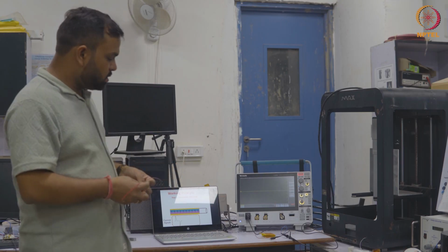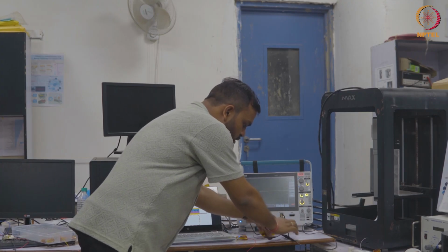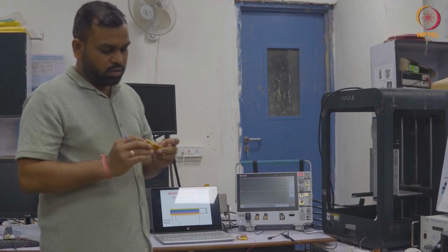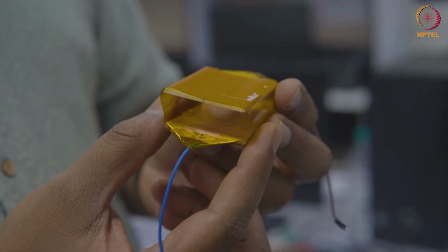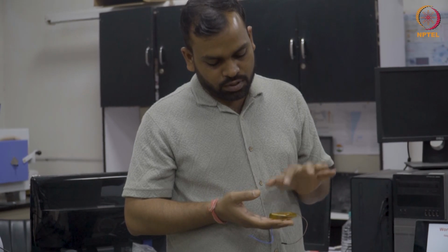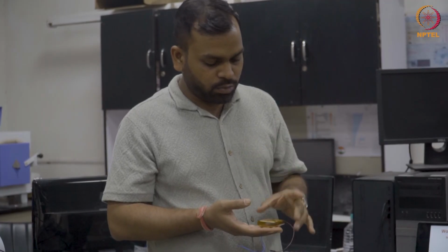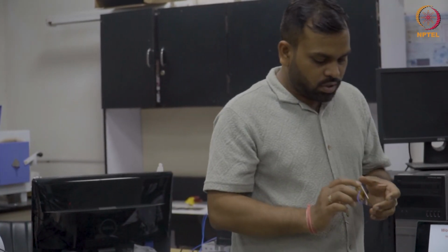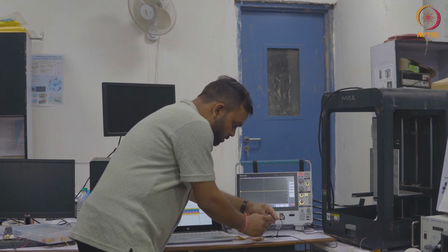We have designed this triboelectric nanogenerator in such a way that it maintains its positions. Now you can see it is in the separation mode, and once the external load is applied, it comes in contact, and once the external load is released, it returns to the original separation position. This is called a contact and separation mode, one dimensional triboelectric nanogenerator. Now we will see the performance of this nanogenerator.